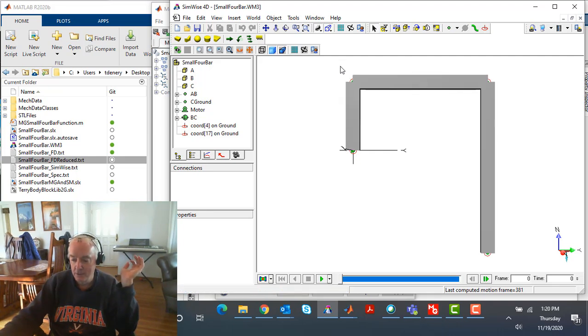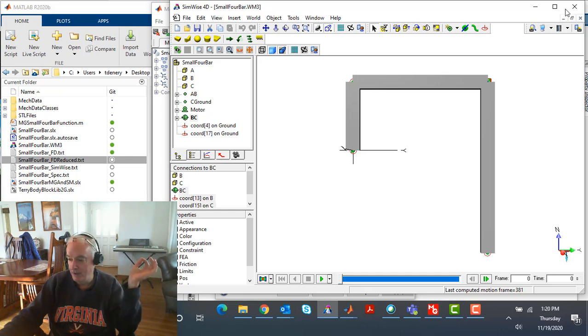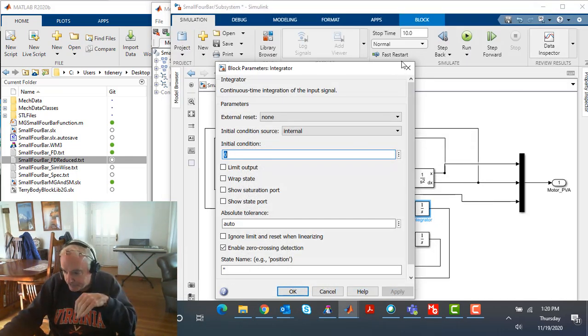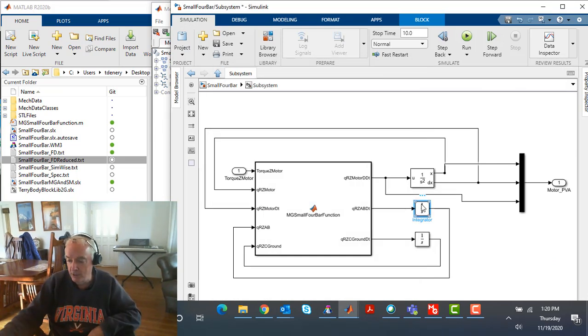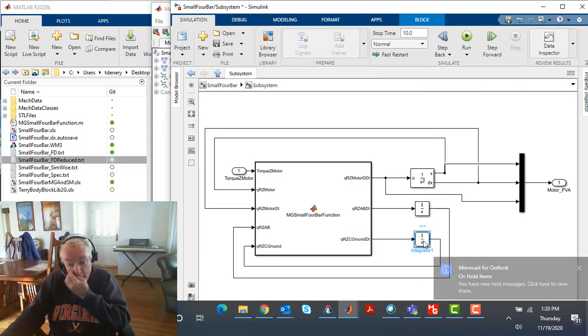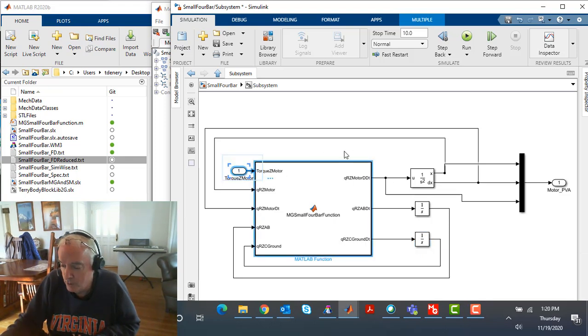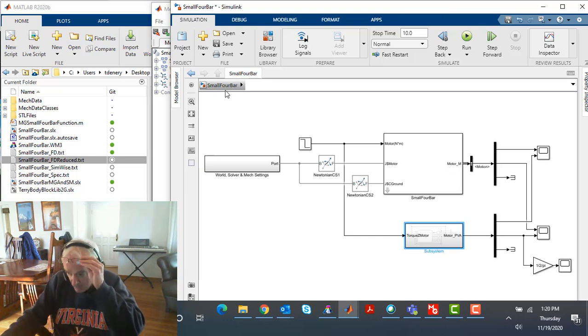So when I set these two angles right here in that integrator, they're each set to 0 by our choice to define the problem that way. And that occurs in these two integrators right there and right there. So clearly it is a 1 degree of freedom problem. It's mostly the motor, and so we drive torque through the motor and we solve for angle and angular velocity with our double integrator right there.